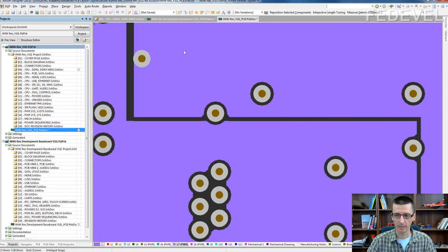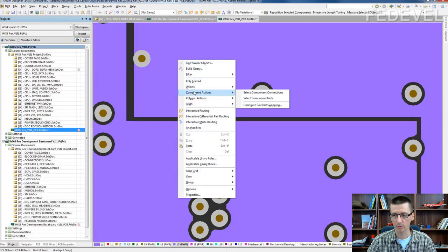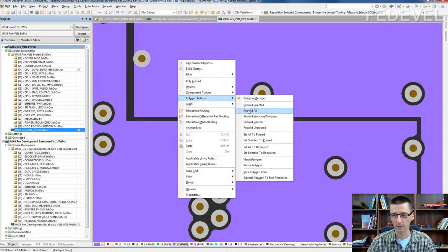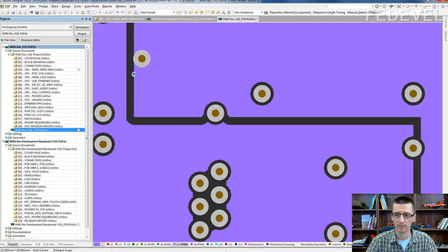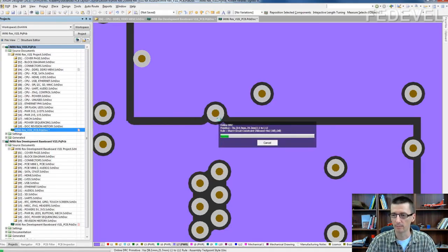Now, if in your design you have on these layers gaps smaller than 0.1, based on this rule, when we rebuild these polygons, it will get wider, you will see. But normally I try to draw them the way they are, the edges of the polygons are at least 0.2 millimeter. See, now it is wider. Based on the rule, it is now wider.